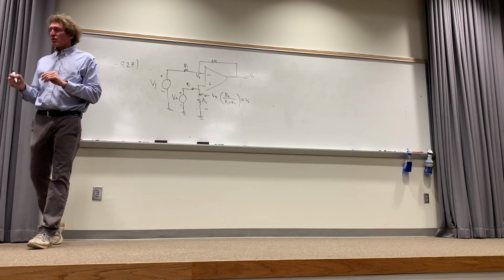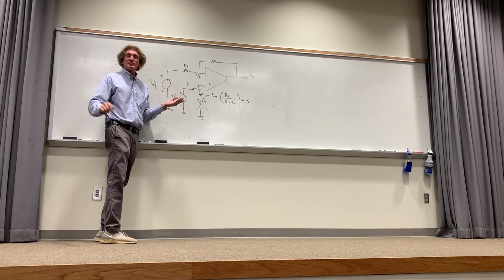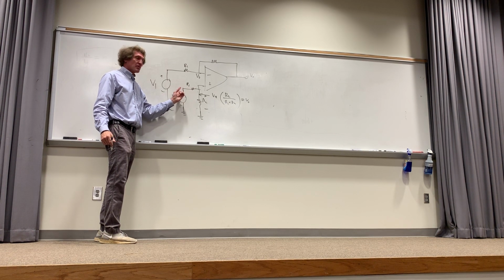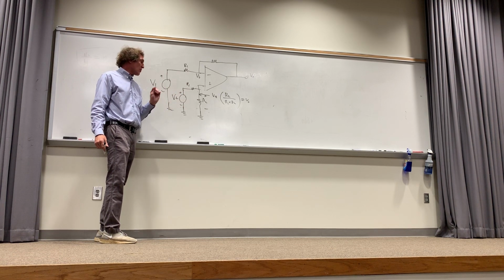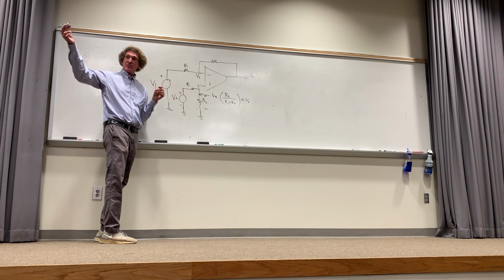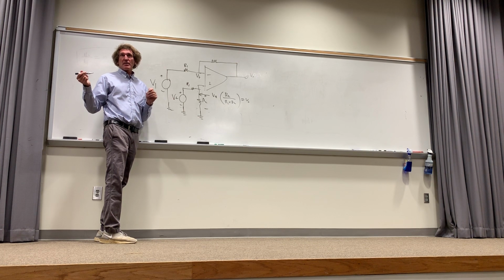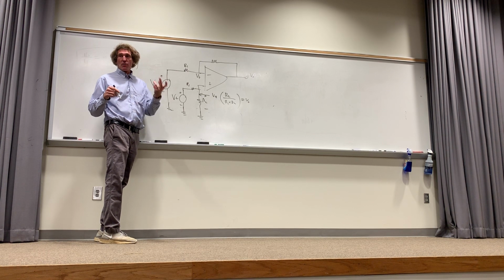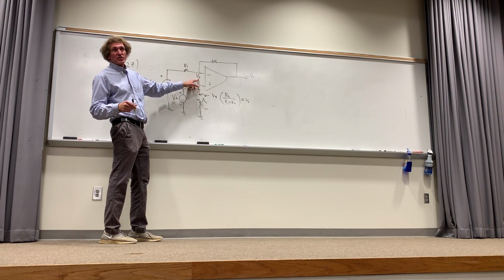Now, voltage division is always something where you take, just think of it, make it as easy as possible for yourself. How much current flows out of this terminal? Well, it would be V2, right, over R1 plus R2, correct? All right, that's the current, V2 over R1 plus R2. So what would the voltage be here? It would be R2 times that. So it's R2 times V2 over R1 plus R2. All right, the bigger the resistance, in a relative sense in a series circuit, the more voltage you get across it. If they're parallel, the less current, right? So that's that voltage.